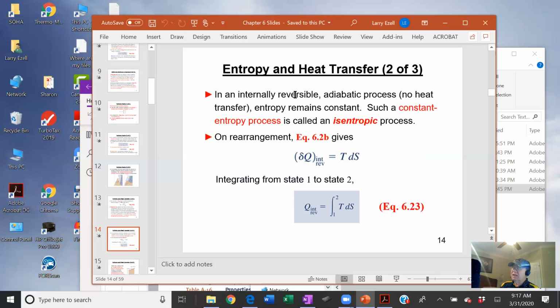So if you have a process that's reversible and adiabatic, even if it's just an ideal process you're doing a mental exercise on to measure the real process against, that implies isentropic. You can't have any two of reversible, adiabatic, isentropic without the third. And that's called an isentropic process.